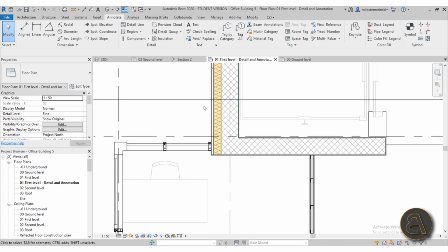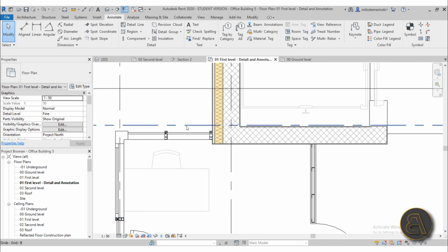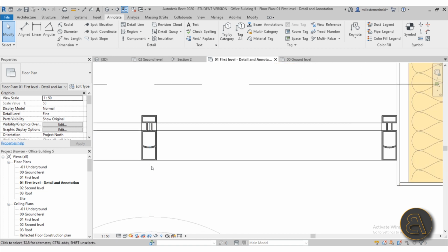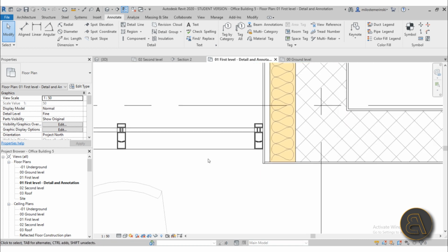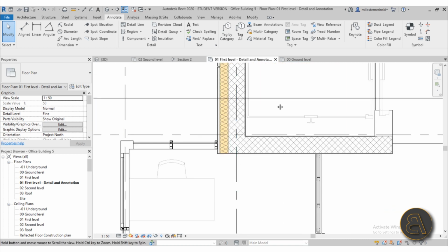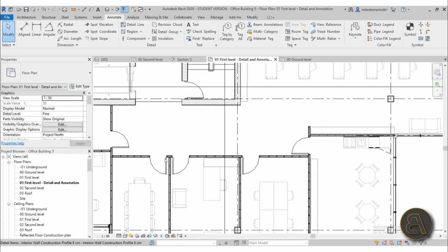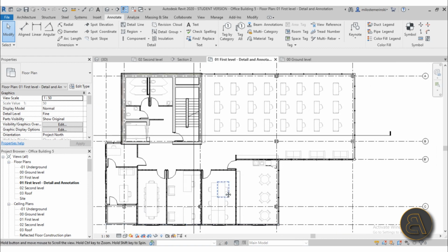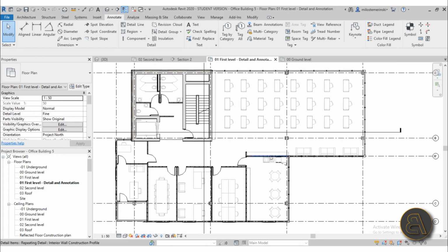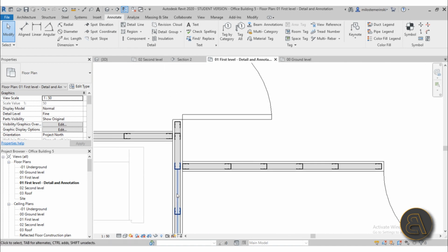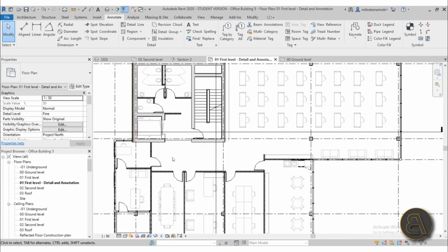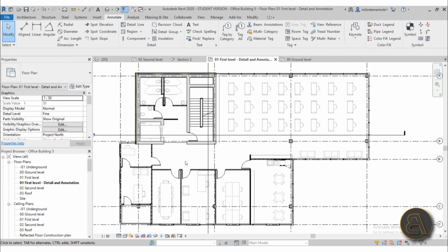And pretty much all of them are connected in a correct way with all of these structural elements inserted. Also, these connections over here are set up, and if we zoom in a little bit to the mullions, you're going to notice that we have created some detailed mullions and a lot of new families that are going along with this project. Also, we've added the insulation line here and many more elements. So I show you in detail how you fix all of this up, how you set it up so it looks really detailed like this, and how you can solve all of these details within Revit. Okay, so that's what this course is going to be all about. So without any further ado, let's get into the course.